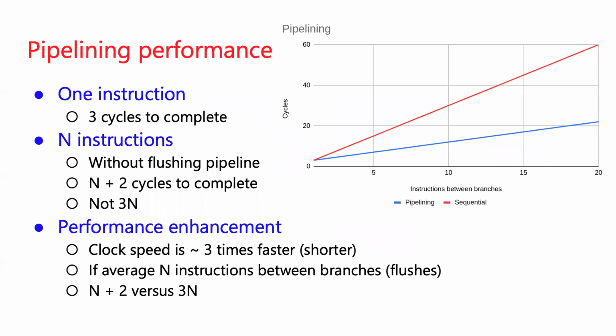If every instruction, let's pretend it takes 3 clock ticks, 1 to fetch, 1 to decode, and 1 to execute. If we had no pipelining, then every instruction takes 3 clock ticks. If we used a pipeline with 1 stage to fetch, 1 stage to decode, and 1 stage to execute, then our execution could get almost 3 times as fast. More specifically, if you had to execute n instructions, then it's going to take 2 clock ticks just to saturate the pipeline, but then you're going to start executing instructions.